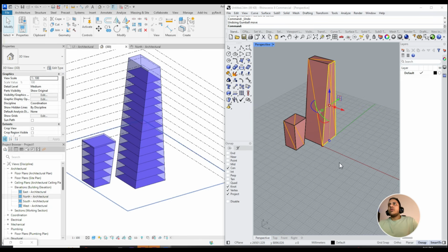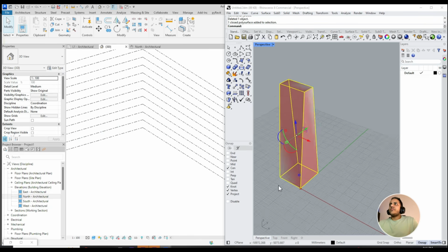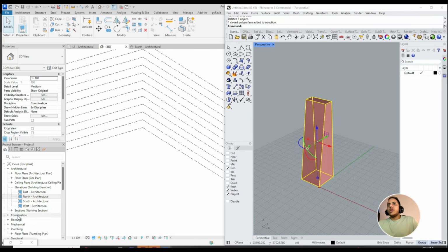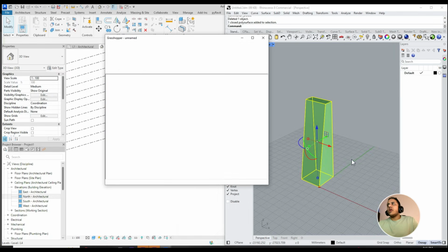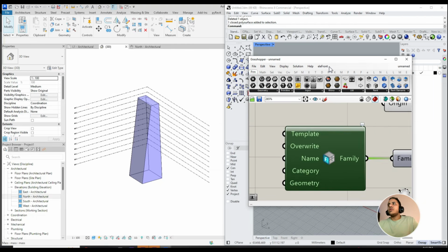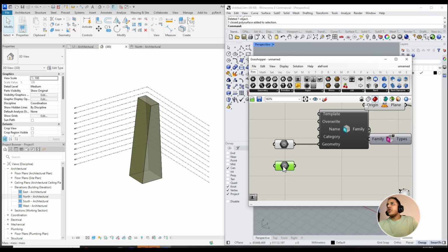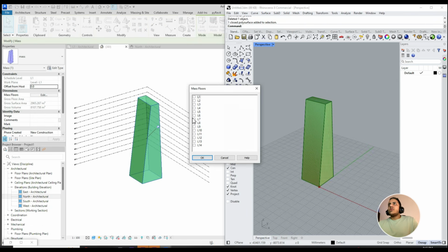Okay, I would like to remove this part. Okay, so Revit will read it as one geometry. In this case, we have to repick our geometry. And if you would like to add another geometry, you can extract this parameter, copy, and come here and select another one and connect it while holding Shift. So let's work on this geometry first. Let's apply the floors again.